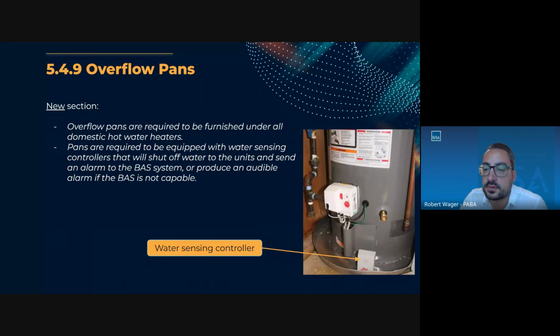Jim had a question, no use of instant tankless hot water heaters. They're certainly encouraged, Jim. In the event you were not using an instant tankless hot water heater and you were using a hot water storage tank like the one pictured here, overflow and leak detection is required. And I'll add, the instant tankless, we're not discouraging them, but again, when you do the analysis, especially if it's a new building, the heat pump versus the instant should be looked at for energy use, efficiency, and life cycle cost.